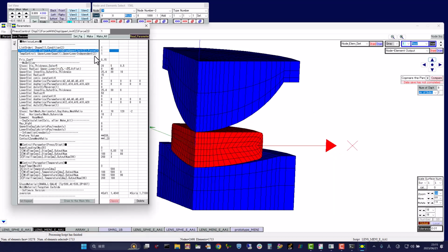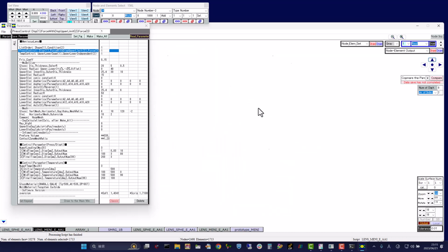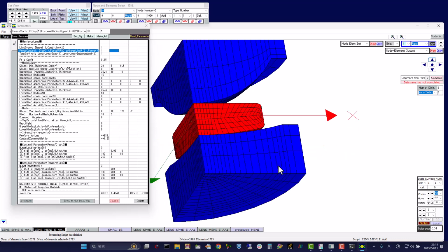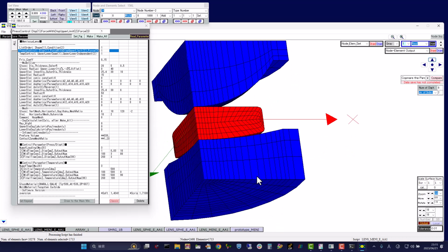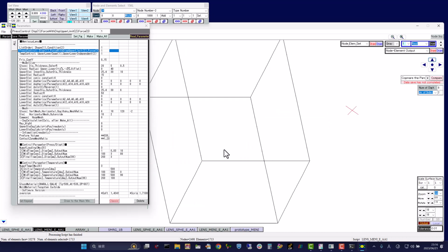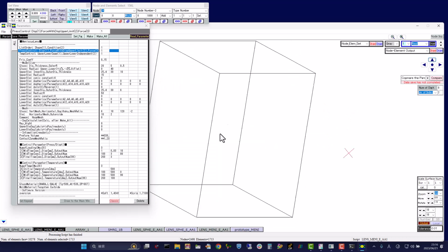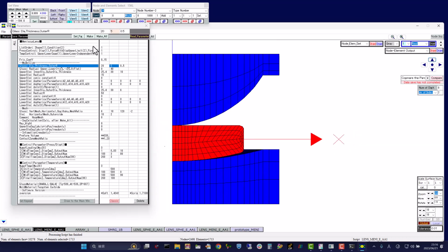Well then, I would like to change parameters of this model and calculate. Before that, I would like to briefly introduce this. Both displacement control and load control are possible. You can choose a displacement. The loading portion of this die is the top side of the upper die and the bottom side of the lower die. It is said that only the same value is applied to both sides. Displacement control calculation is generally better than load control in terms of stability. On the other hand, force control is more practical. Displacement control is more stable, so today I would like to demonstrate with displacement control.